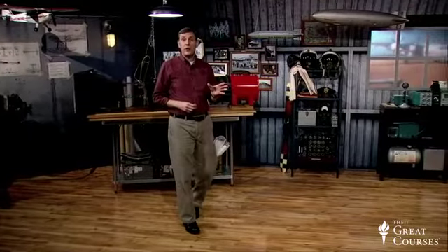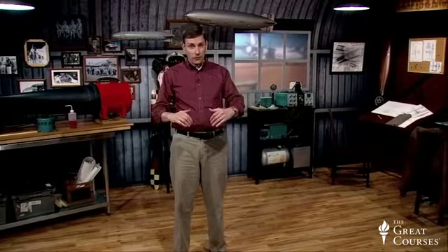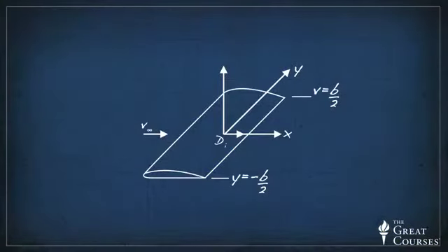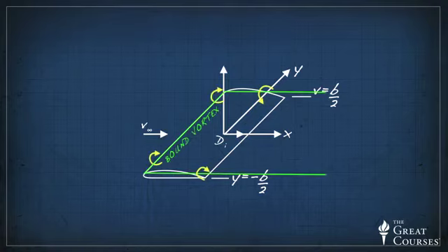One analytical tool was developed in the early 1900s by researchers in Germany. Led by a distinguished scientist named Ludwig Prandtl, they came up with a description of lift based on a bound vortex on the wing, called lifting line theory. They basically came up with a way to model the induced downwash of the flow over the wing and the strength of the tip vortices. Imagine a horseshoe-shaped vortex filament extending along the span of the wing and trailing from each wingtip and extending downstream to infinity. This seemingly esoteric construct was actually extremely successful in describing the amount of lift generated by a wing and is still used today for first-order analysis.